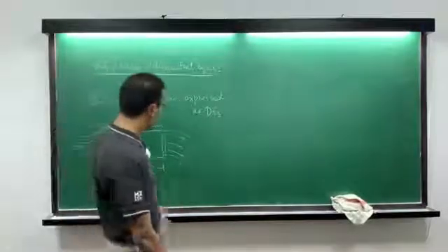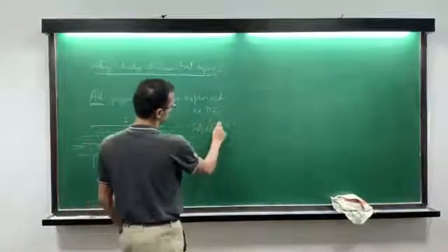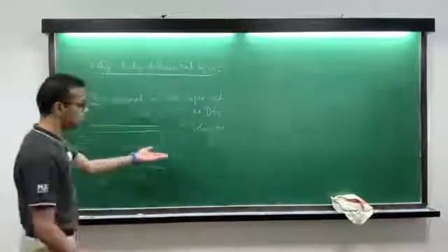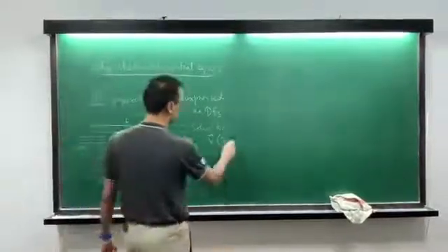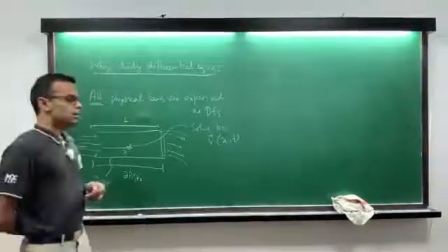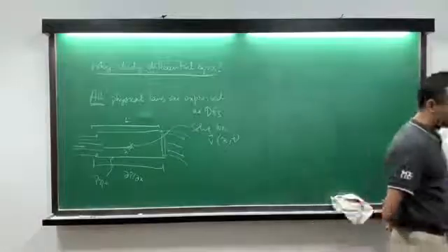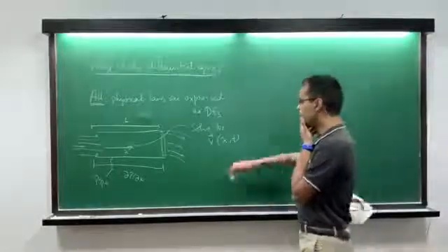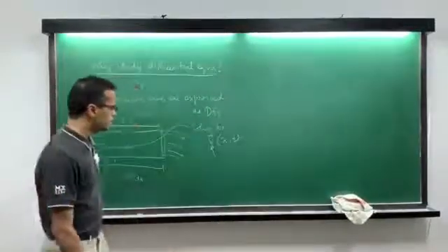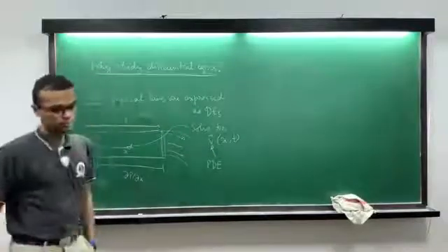So in this situation, solving for the velocity field at any point, again the velocity field will depend on where you are along the pipe a priori, and it will depend on the time. Since it has dependence on two independent variables, the governing equation will be a PDE. Again, it will look like a diffusion equation in this case, but it doesn't matter. It will be a PDE that governs V bar.